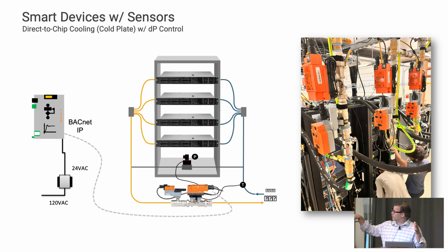Because really each and every one of those represents an identical CV. So if you know DP, you can figure out the flow across all the various racks. We tried to sell them on pressure independent solutions, on flow monitoring solutions, but you can't do that for every single rack. Go back if you would.